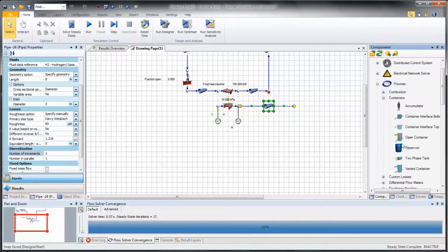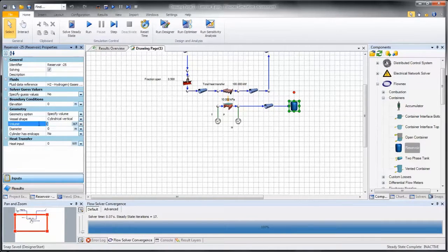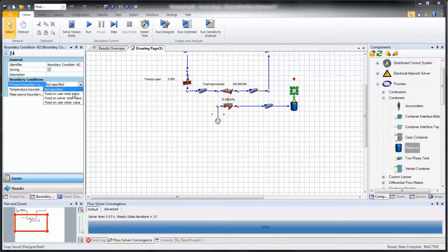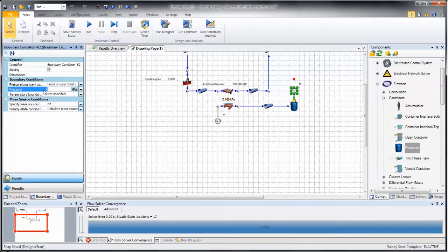Next, I'll add the reservoir with a chosen volume of 3 cubes and diameter of 1. You could have selected anything sensible here, since it wasn't specified. I have to move the boundary values, but since the pressure on the tank is part of the problem specification, I'll change the boundary value option to pressure and specify a value of 1000.